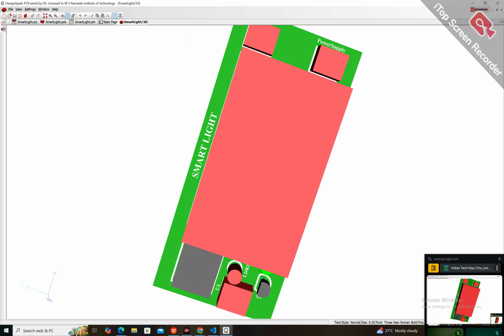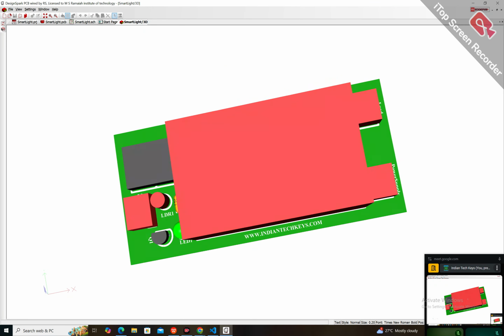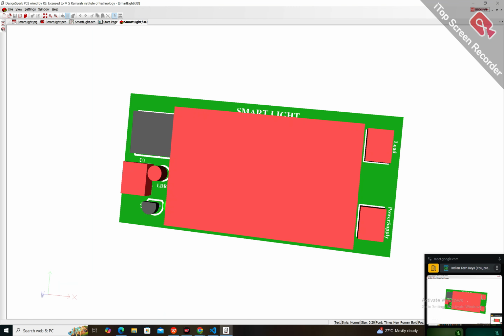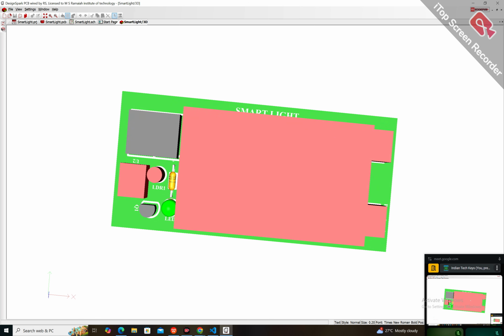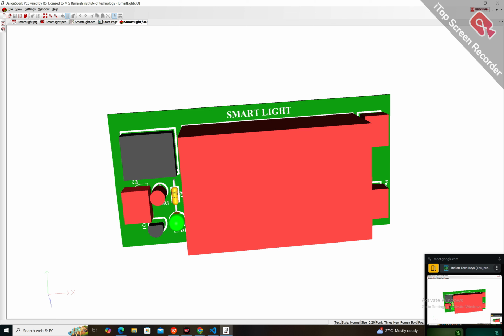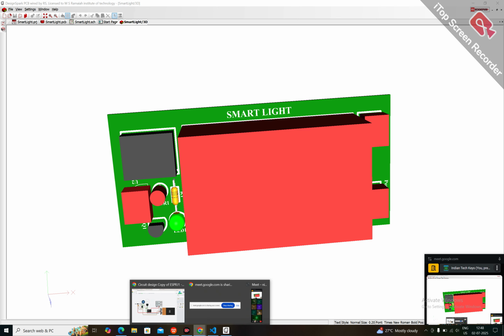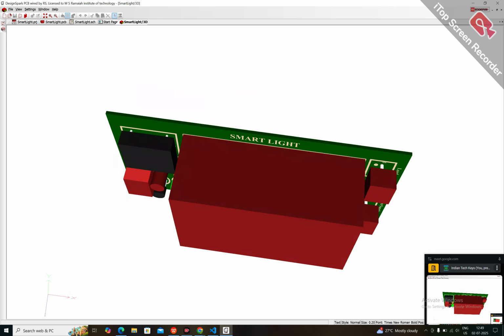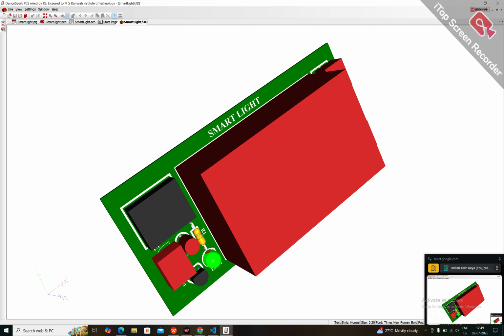So that's the reason in many colleges I suggest letting students design a PCB for their project. One challenge students face in PCB technology is the cost of fabrication. Generally, if you give this particular board for fabrication, you may not get just one or two boards, because a manufacturer like us won't accept orders for only one or two boards. There is a concept called engineering charges. The first thing is you are going to bear a charge of around 2,500 rupees for engineering setup. Engineering setup means the diaphragm and many other things they manage in order to develop a PCB. So engineering setup, followed by the board, based on the board size they are going to charge.